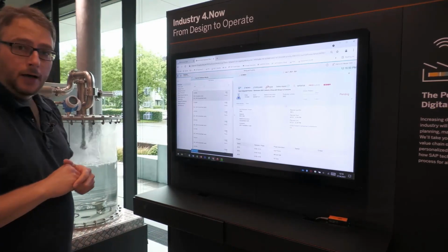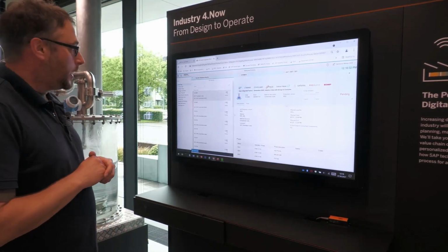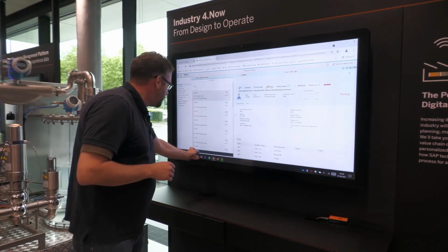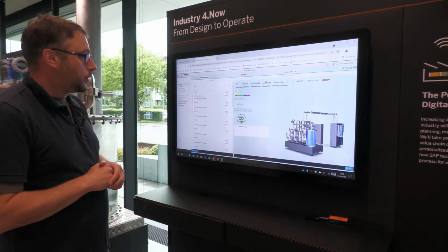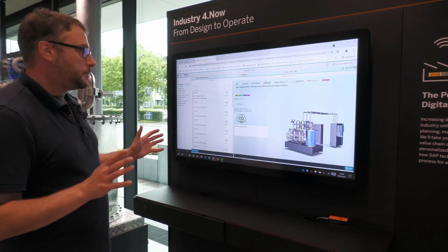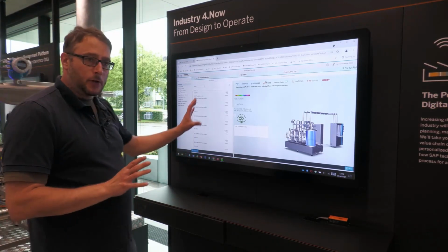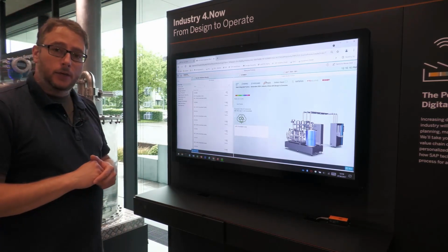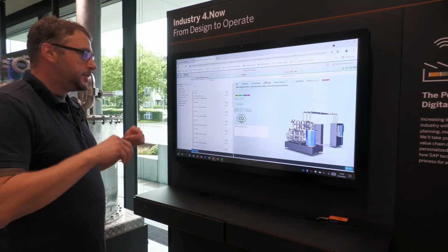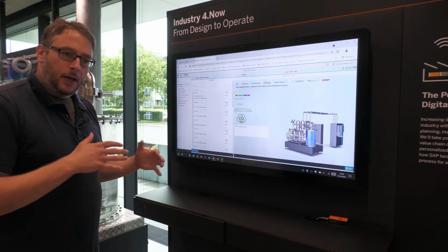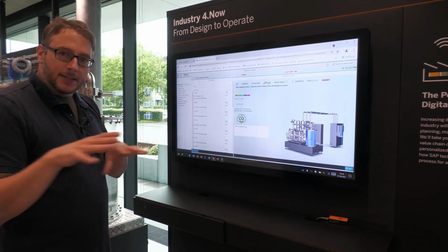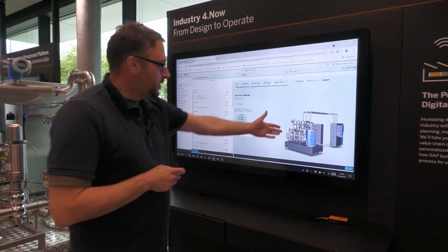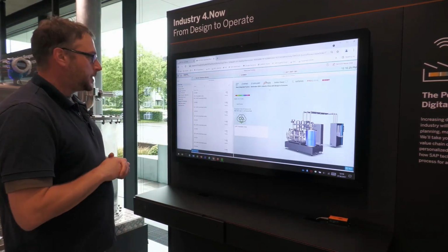You see here a classical SAP environment where we would say, for example, let's create a new production order, a new process order. And as I said, it's a little bit of a mock-up, but the principle that we communicate between the IT world and the automation via OPC UA is built in, and that's no mock-up. So all the architecture, the layering, is like it would be in real life. It's just that nobody produces with this dummy machine called EvoMix.